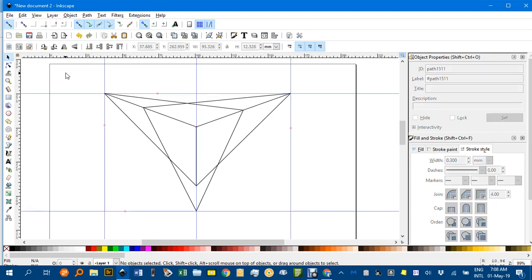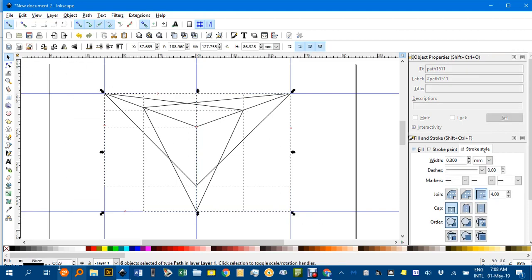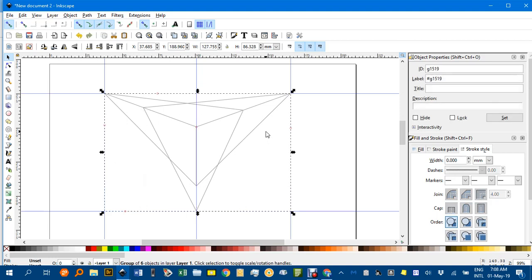So what I'll do is I'll select all of those, change the colour to a light grey, shift click that, excuse me, and well actually I've selected also the shape lines as well as perspective lines. You might want to just hide one or the other, but that's okay. I can control group these, and I'm going to lock them. Bring up the object properties, Control Shift O if you need to, and click lock if you don't want them interfered with. Actually, I'll take the lock off. I think it should be alright without that.